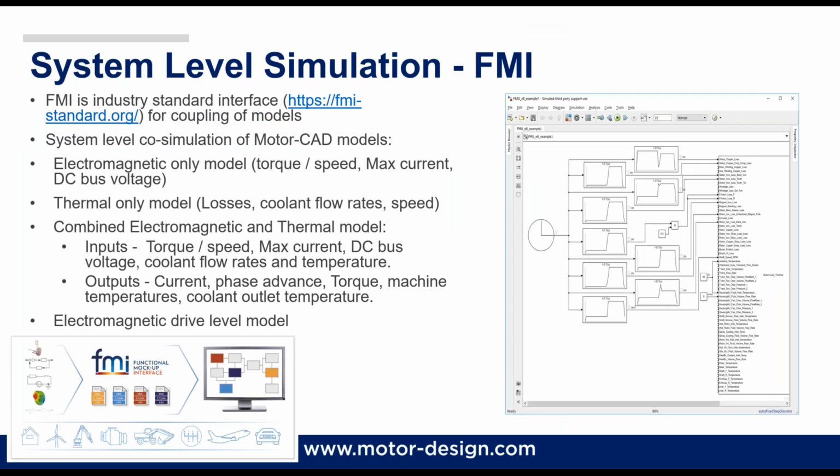Here we have another useful coupling provided by MotorCAD, which is the link with the FMI, which means the Functional Mockup Interface, which is an open standard for exchanging dynamical simulation models between different tools in a standardized format. The FMI standard specifies the FMU, which stands for Functional Mockup Unit, which is a file with the extension .fmu that contains a simulation model that supports the FMI standard.